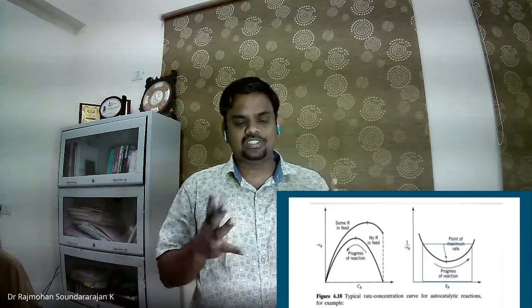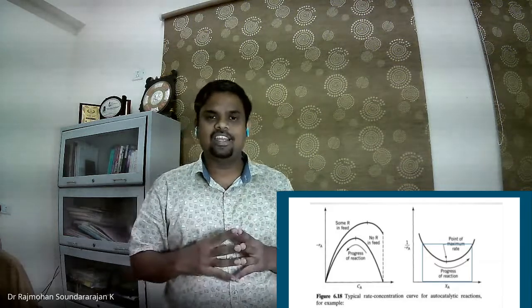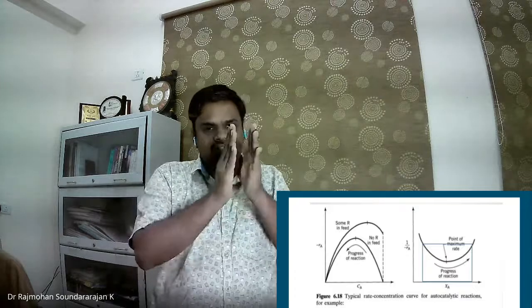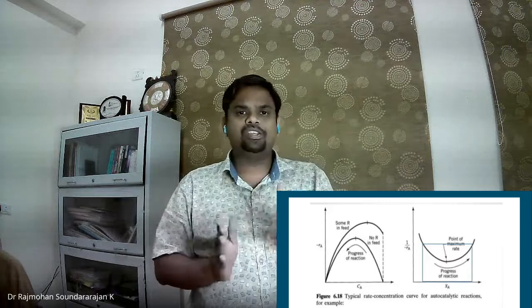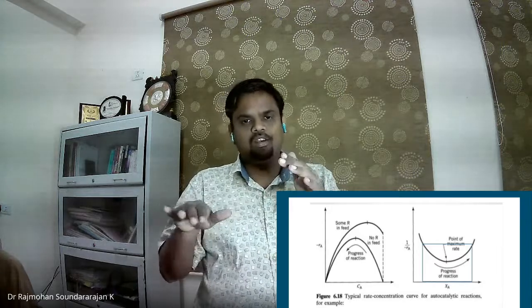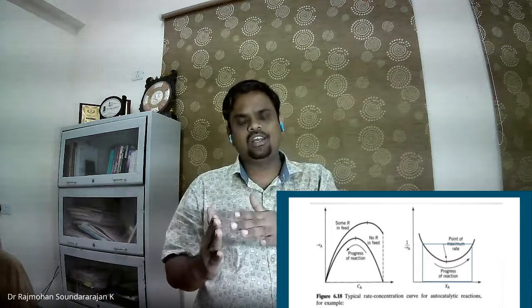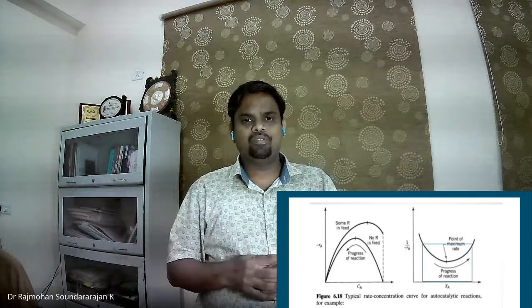So now this is the case, right? We have autocatalytic reactions and we have three preferences. For low conversion, CSTR is preferred. For high conversion, plug flow reactor is preferred. Or if you want to have a combination, up to this peak where you have maximum rate, CSTR followed by PFR is preferred.